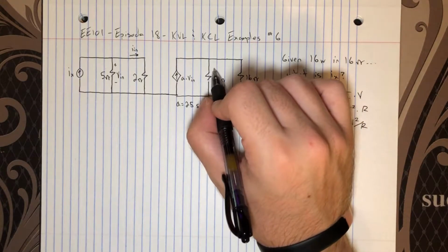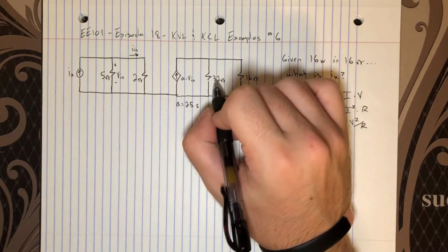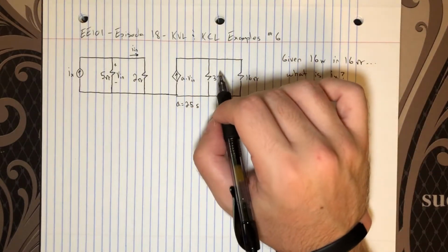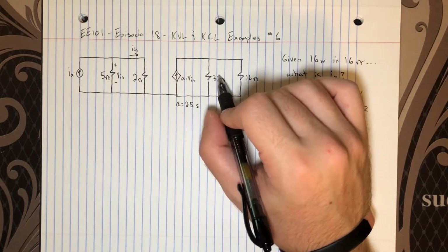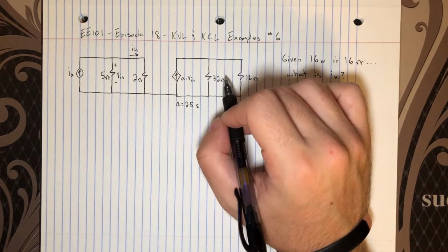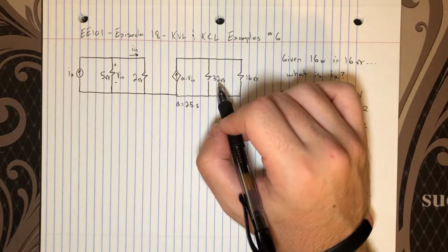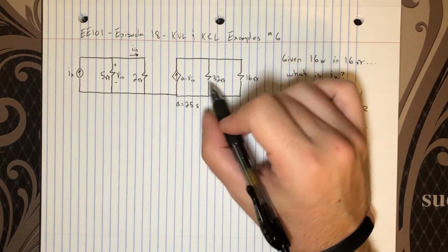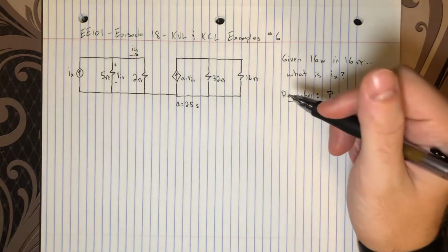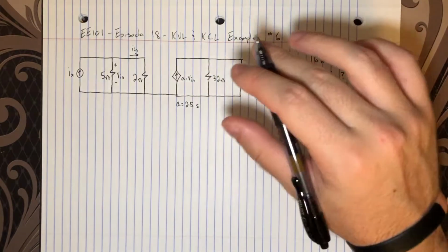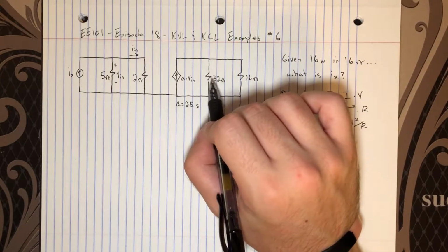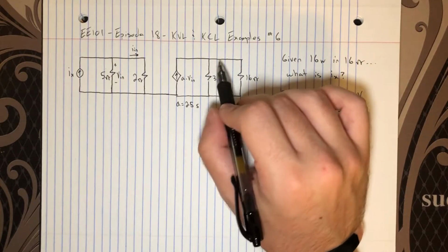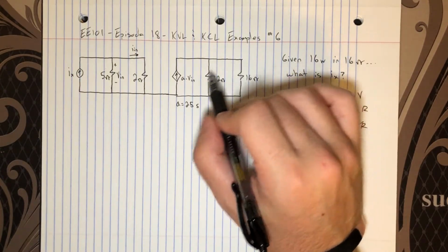And so we know the voltage on at least one of the resistors has the positive polarity on the top side. But then, of course, we automatically know the voltage polarity of the other resistor because they're in parallel, and they must share the same voltage because they're shorted together on both sides by ideal conductors. So I know for sure that the current in both of these resistors is flowing downward because they both have the same voltage, which is positive on top and negative on the bottom,